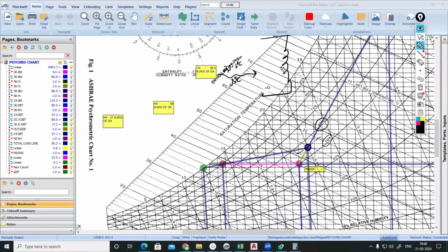On that state, air will be touching the cooling coil, and the cooling coil has to cool the air until this point. So that much dehumidification has to be done as per the humidity ratio to be achieved. Then from this state, we have to cool it until this point, and the process has to be continued until this point. So this is the coil capacity.